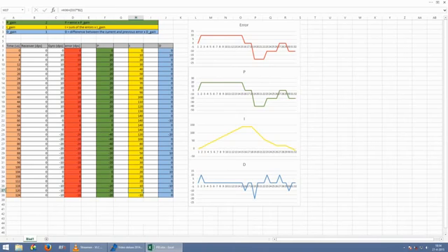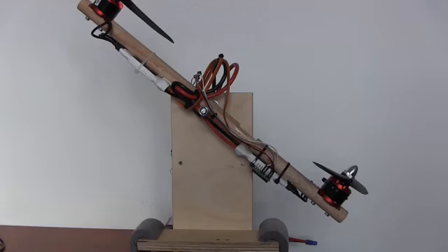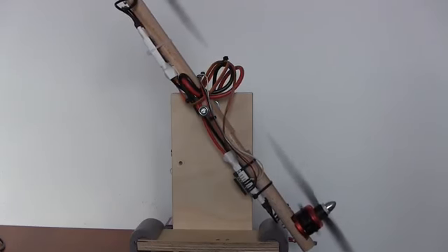The D controller is somewhat different because it only reacts on a change of error. As you can see in the graphics, it only reacts a few times at the start of an angular motion. Now this might not look interesting, but this controller is very important for our multicopter. Because there is no friction, the multicopter easily overcompensates as we saw before. When set up correctly, the D controller gives just enough, so to say, friction to prevent the other controllers from overcompensating. The results on the test stand are pretty funny to see.